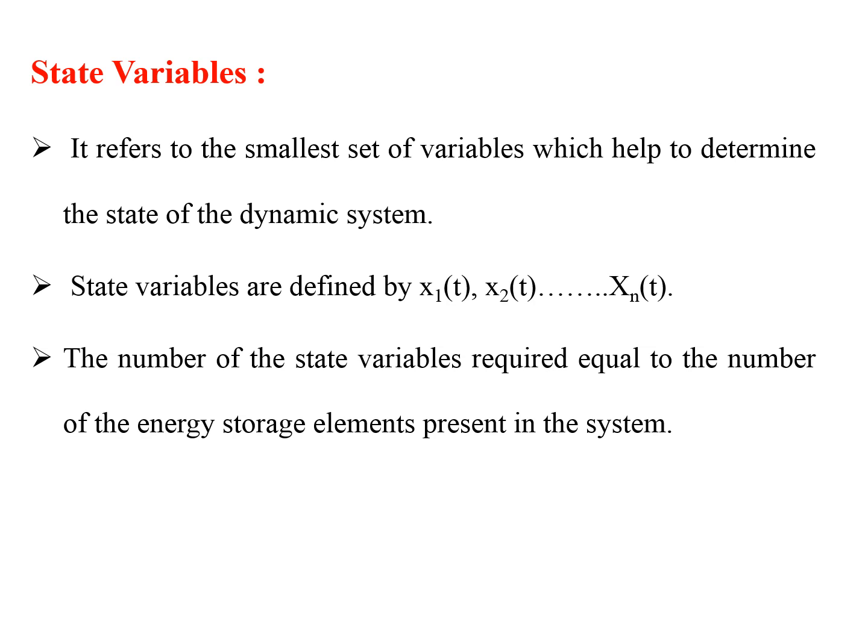Generally, in electrical circuits, we consider the energy storage elements as the state variables in the state space analysis. That is, energy storage elements in electrical circuits are nothing but the inductor and capacitor. The inductor stores the energy in a magnetic field and the capacitor stores the energy in the form of an electrostatic field. The current flowing through the inductor is considered as one state variable. Similarly, the voltage across the capacitor is considered as a second state variable in electrical circuits.